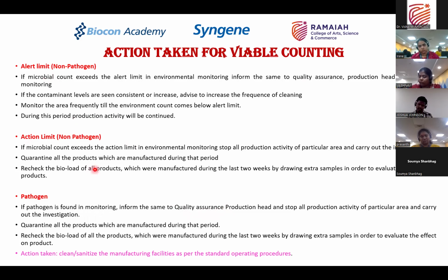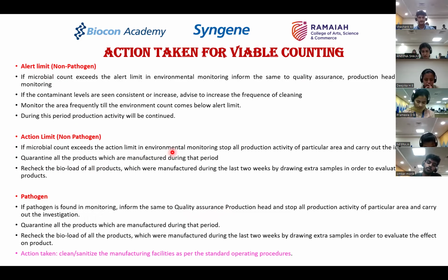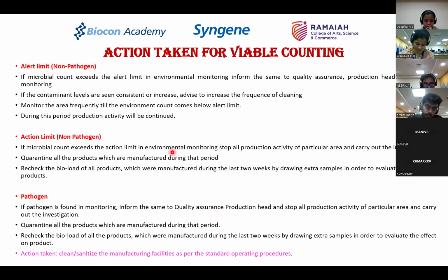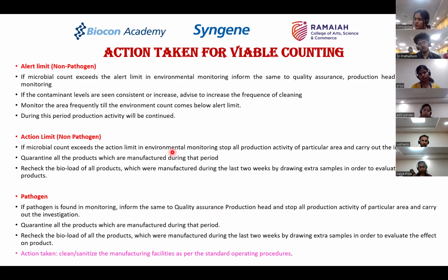If the microbial count is increasing beyond the action limit, there are very important steps which have to be followed. First, production should stop. The products produced during that time should be quarantined, and the products from the 2 weeks before that point should all be evaluated for the same effect.